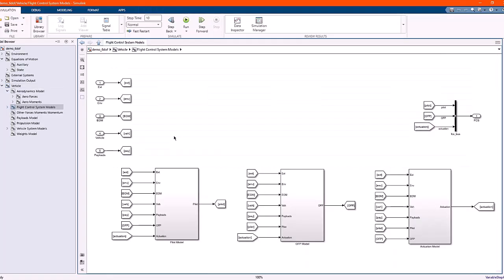The flight control system model includes empty placeholder models for the pilot, the operational flight program, and actuation. The pilot model simulates onboard pilot inputs. The operational flight program contains models for automatic flight controls, stability augmentation systems, etc. These models can be developed using Simulink, compiled S-functions with actual software, or even connected to actual hardware. The actuation models simulate actuators and linkages for flight control surfaces, high lift devices, braking surfaces, thrust vectoring, etc.